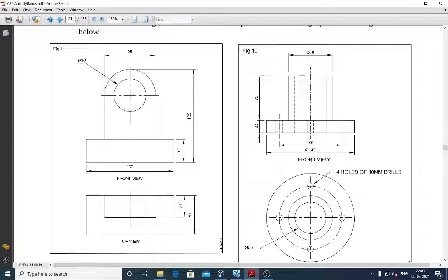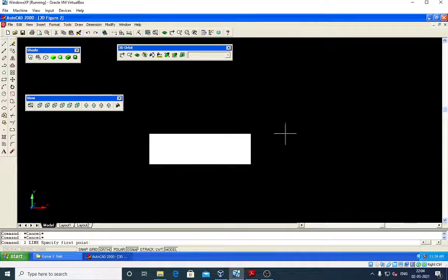But I would like to draw one rectangle where from here to here it is 25 mm. As you know, this arc dia is 50 mm, whereas this is a radius, so I will take it as 25. From here to here it is 25. So out of 75, 25 is reduced, so that from here to here you are getting 50 mm. So I will draw a line of 50 mm side, and height is also 50 mm, and on the right hand side, left hand side it is 50 mm, and on the bottom also it is 50 mm.